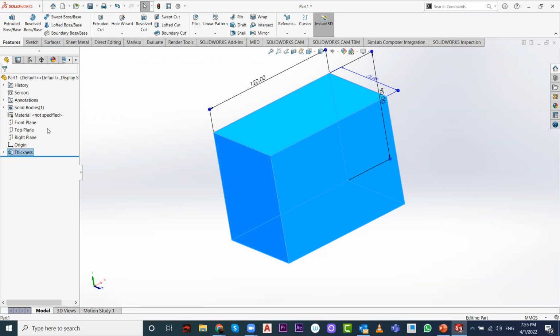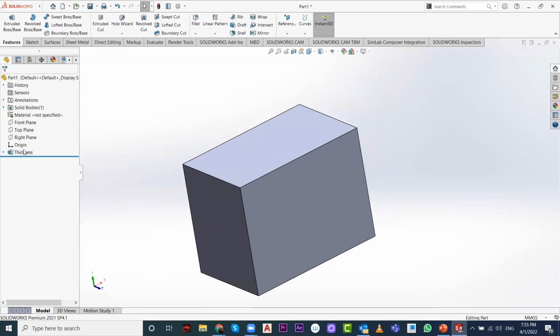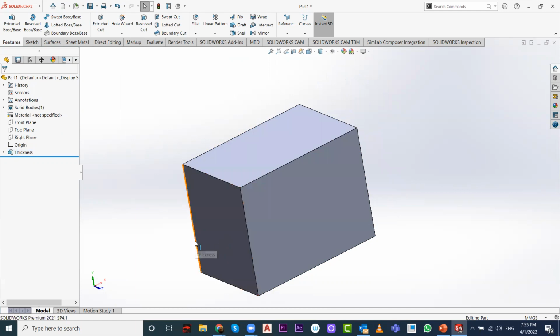Okay, or thickness 1, whatever. So you can double check and change the feature name here. This is called the feature. To master this simple application, this SolidWorks application, the key is just differentiating between the feature interface and the sketch interface. This is like a nutshell of SolidWorks.